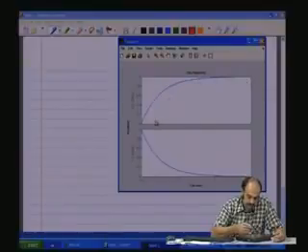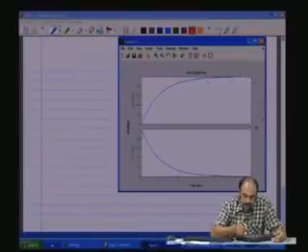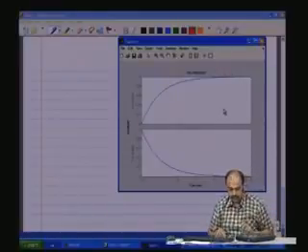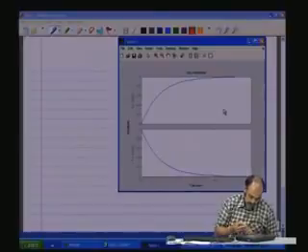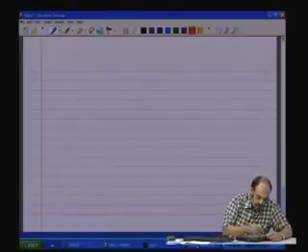And here, of course, we see that this is rising, and now when you remove the input, when you make it 0, you will see that this will decay, and the output will exist, meaning it will not be 0 even when the input is 0, and therefore, the gain will be infinite. So, the existence of the pole and the zero. So, let us just have a bit more consolidation on this pole zero concept.